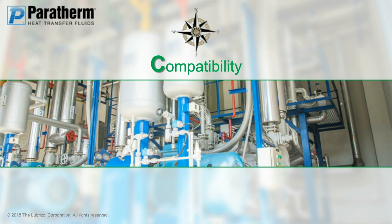What's more common, though, is when someone's changing out a degraded fluid and switching to a new one. Oftentimes they use a cleaner or bring somebody in to apply a cleaner in between the refill. Be very cautious of what that cleaner is. If it's an aqueous-based cleaner, don't do it. It's going to cause more headaches than it's worth. If it's a solvent-based cleaner, you need to make sure that that solvent's not going to cause problems to the new fluid when you put it in. And then, of course, there's moisture contaminants that can happen when you leave a system idle for too long as well.